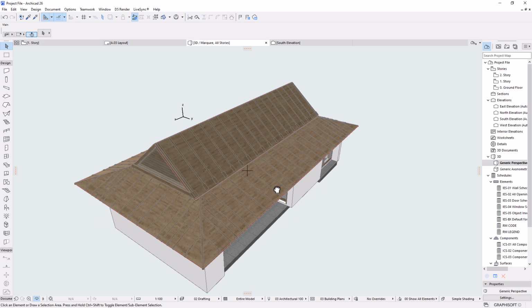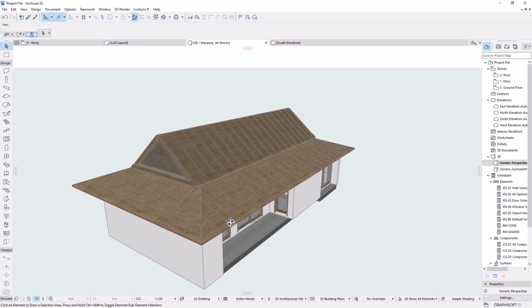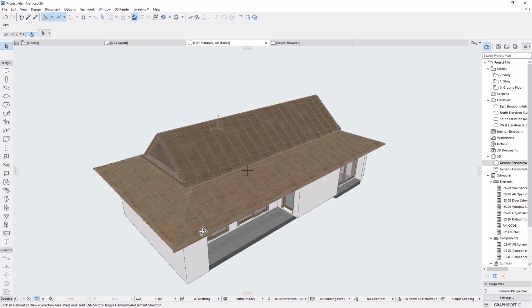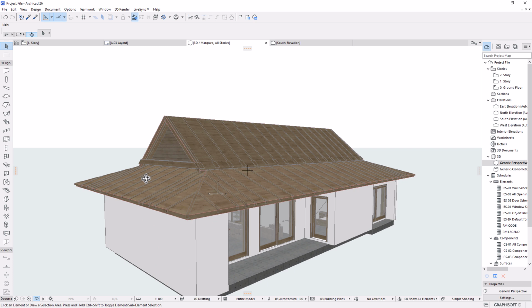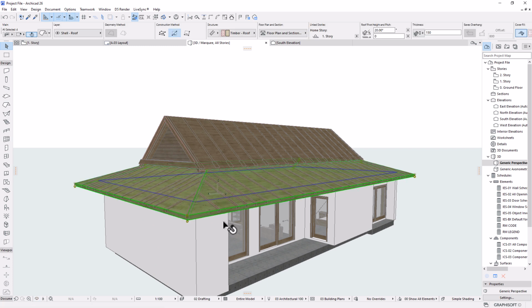Let's move forward again and add more details to this roof to create a 3D detailed or realistic roof finish, because as it is now, it doesn't have a finish. This acts as a roof structure, but it's not a finish. To do that, I would select all the roof planes again and make sure the suspend group is active. I don't know, that could work while the elements are being grouped. Let me just try it with you guys here.